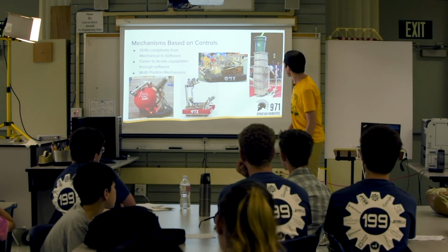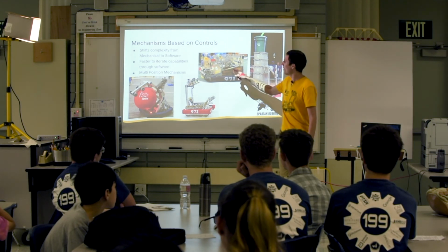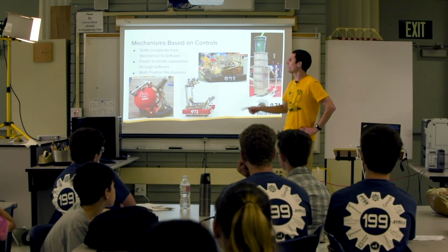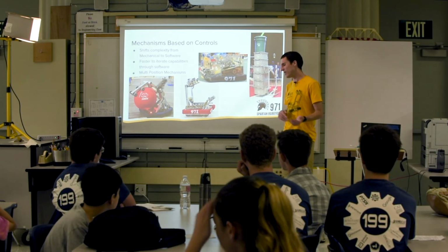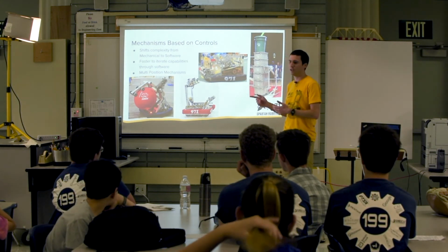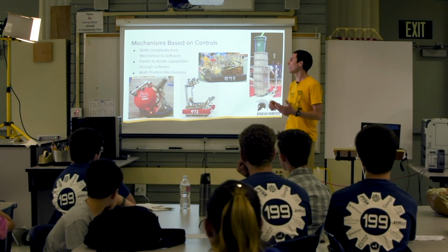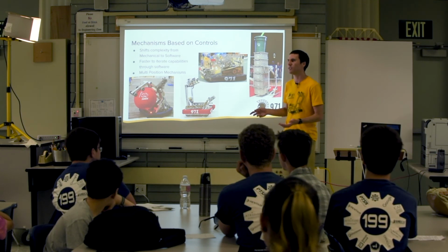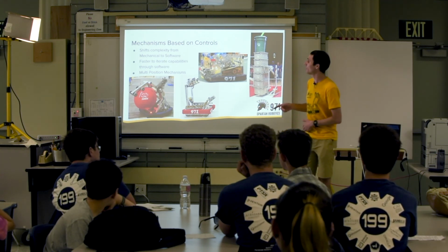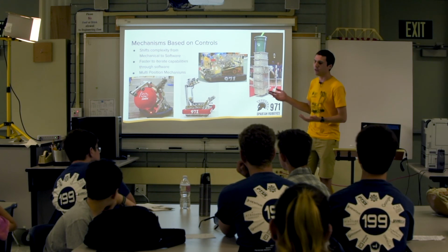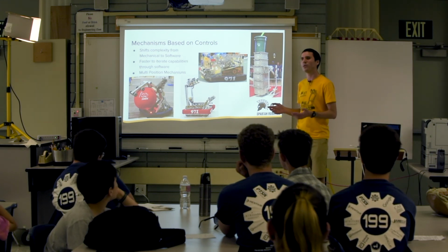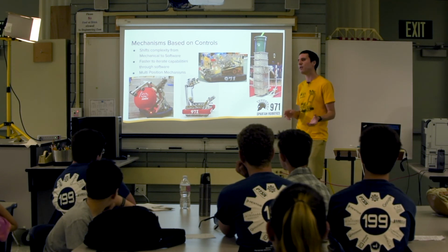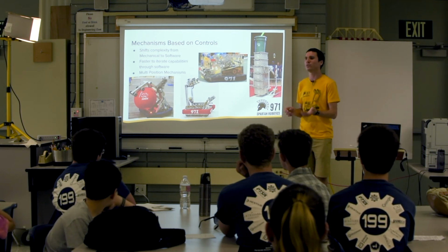If we look at our 2017 robot, we have a hood on there and a turret for our shooter. We said, hey, let's do a shooter hood and a shooter turret, because that way we can have more flexibility in how the game's going to be played later. We can shoot from any position. Another reason we have a hood on there is that we did a bunch of testing on what we wanted our shooter geometry to look like, but we knew that we wouldn't get the hood angle just right the first time.